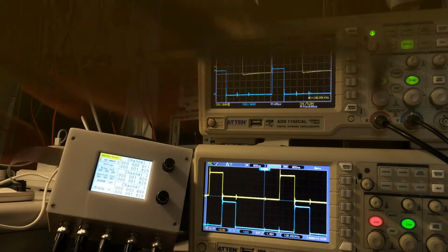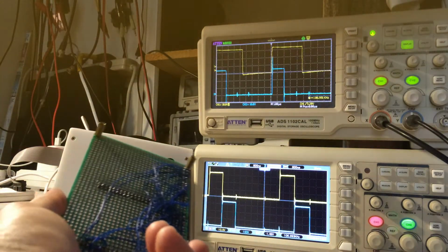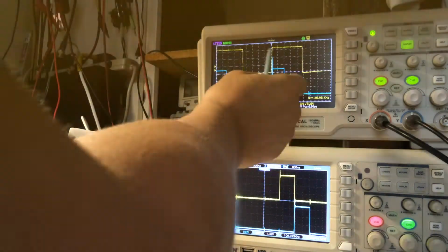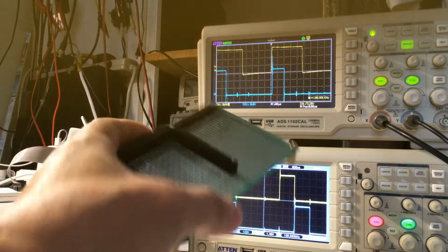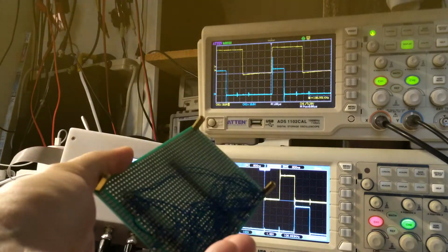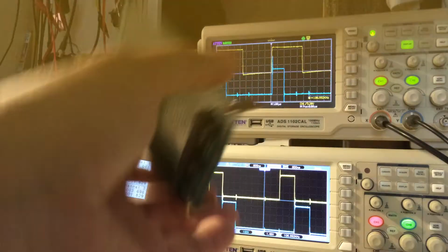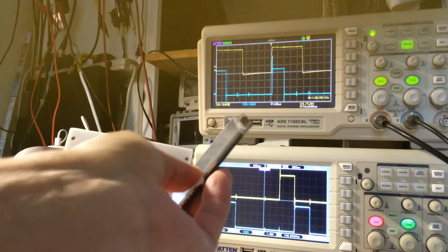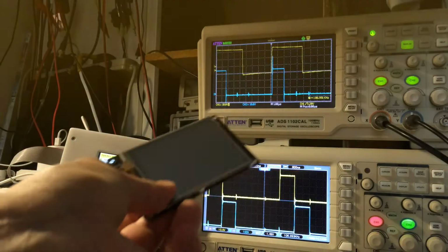I have some kind of cross board. Unfortunately, I use wires to connect it, and this is because you see some kind of artifacts on the signal. It's very small, it does not depend on the work, but if I make a normal PCB with a ground layer, I think these small things will disappear. And this is a TFT screen with touch screen function. So these are the three main parts of my system.